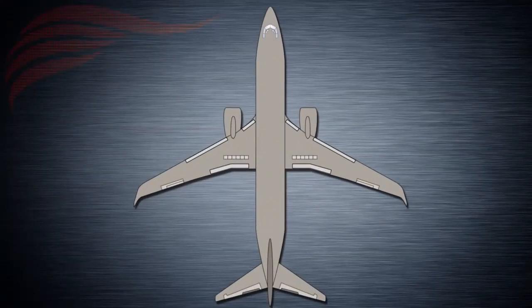Flaps and slats in the 737 NGX can be grouped into two categories: leading edge flaps and slats, and trailing edge flaps. In the leading edge, there are 2 flaps inboard of each engine and 4 slats outboard of each engine. This configuration is repeated on both wings. In the trailing edge, there are a series of flaps both inboard and outboard of each engine.